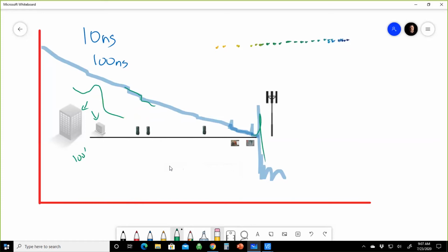And so that's the problem with pulse width. As you increase the pulse width, you'll get more distance out of it, but you sacrifice resolution. Can I see two events that are close together, or does it merge it?